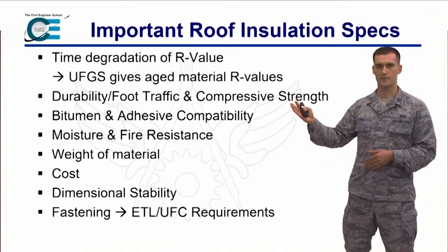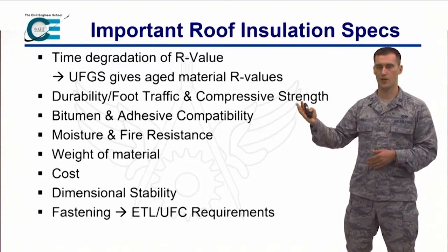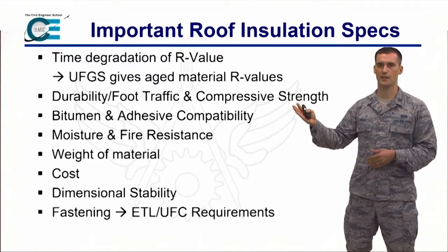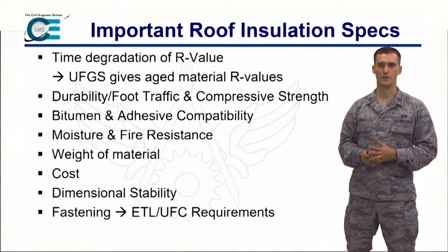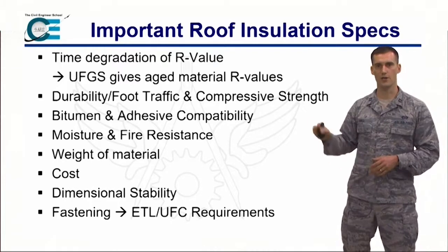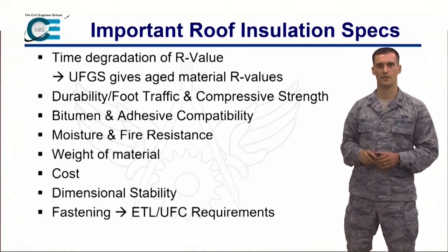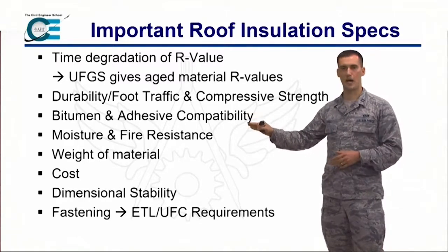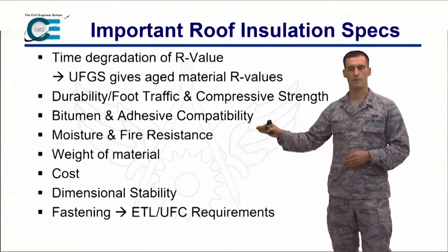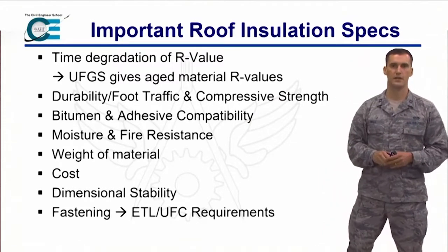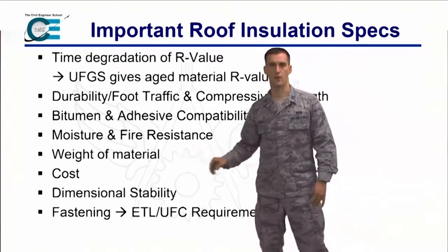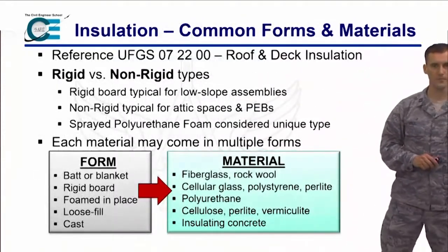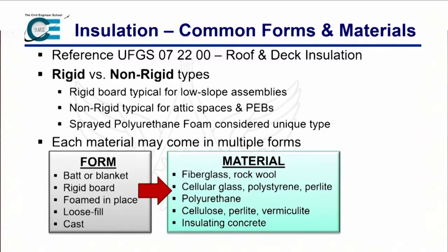But there are other factors that we need to consider. For instance, if this is a flat roof, you're going to have foot traffic, and so compressive strength is going to be important. You can't just have a flexible insulation installed in a built-up roof where you're going to be walking all over it. You need to have compressive strength and rigid insulation up there. How well does it respond to heat? If we're using hot bitumen or adhesives, it needs to respond to heat a little bit. And obviously, cost and some of these other factors are going to weigh in significantly as well. So those are some of the metrics, the specifications that you'll see when you look at insulation.